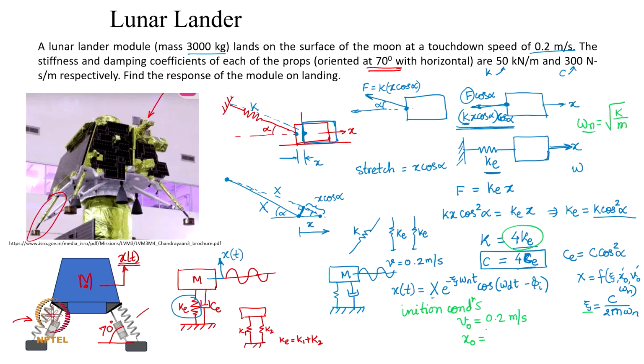Now, you may notice here that when it touches down, we have assumed that these props are fully stretched out, right. That means they are not compressed. So, the springs in the props are outstretched and the mass is sitting here. Okay. So, it is still to touch the ground, right. When it is not touching the ground, we are assuming that these are fully stretched. The moment it touches down and the mass exerts its weight on the spring on all the 4 props, there is going to be a shift in the position of the mass, and that, if you remember, we mentioned as the static deflection.